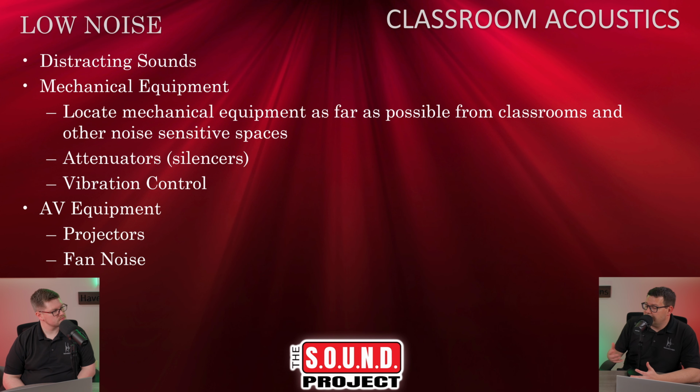Also, you can put attenuators and silencers in the duct path to make sure that air noise is not going to transfer through. And then there's also vibration control, because anytime you have something that's vibrating and potentially resonating the structure, if you can cut that out at the source, it's going to be a better result for everybody. Other noise sources would be like AV equipment. So it could be projectors, or it could be audio equipment that's in the room that has fan noise.